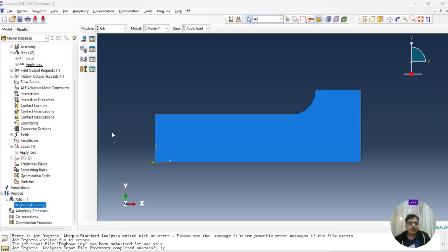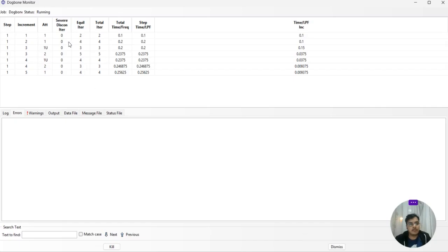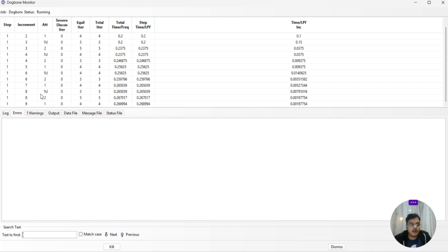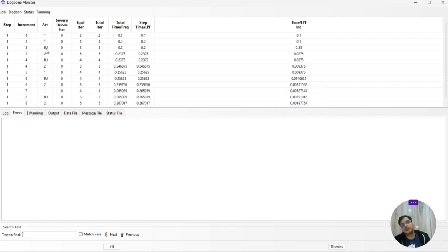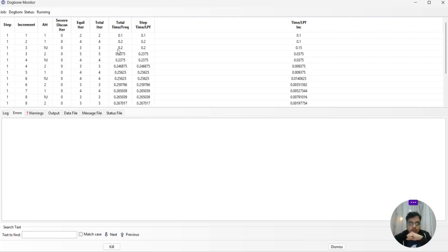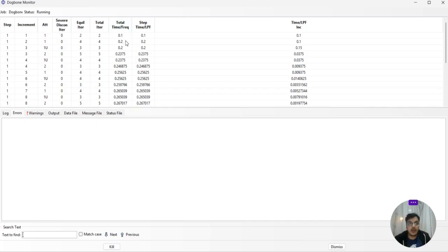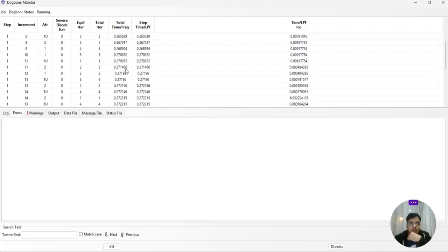So once it starts running, we can also understand one more thing, that is the unsuccessful attempts given by the Abaqus solver. Make sure whenever we have this one U, it means the system has given a particular time step to it. Let's say we define, if you remember, we defined earlier a 0.1 time step, but unfortunately at that particular time step, the initial was all okay. Hold on, it's just running, trying to get to 1e minus 10.